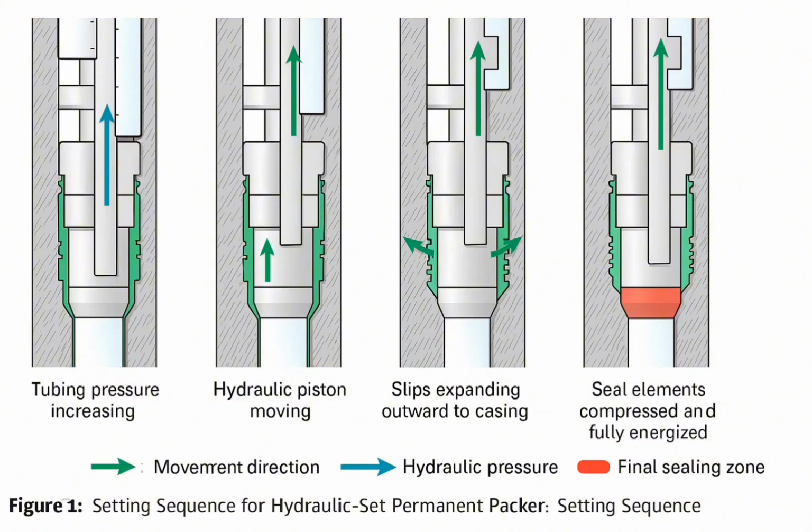The visual clarifies that hydraulic set packers are ideal for deviated and horizontal wells because the setting force is independent of pipe movement. It also emphasizes the criticality of proper pressure application and monitoring during deployment.